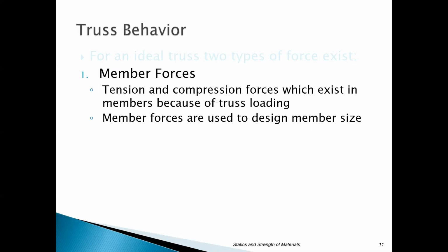And why we need this member force concept: when you get into the strength of materials aspect, knowing what kind of material you have and what kind and quality of force, whether it's compression or tension, is going to allow you to size that member. So do you need an I-beam that has a depth of 12 inches, or do you need an I-beam that has a depth of 15 inches? That will be determined by the forces that you're going to come up with in the members. So we're going to start to get into that kind of stuff when we get into the chapters later on in the book.